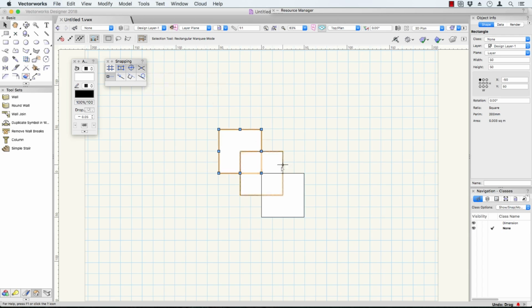So if I go near the intersection of 2 objects, top center is already there, but if I had gone there, I would have got that as well. This is my smart cursor settings. So the smart points, or the smart cursor, is the part that allows you to touch a point like that and then line up with it. So you can line up with objects, which really speeds up your drawing. It's a really dramatic speed up if you can learn how to use that. So let's look at these in detail.